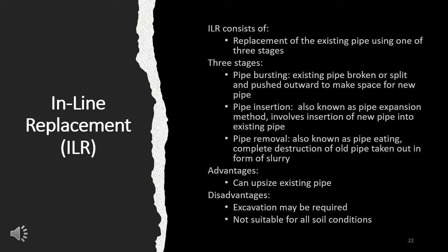Now, some of the advantages of using this replacement technology is that we can upsize existing pipe. The disadvantages, however, are that excavation may be required and it's not suitable for all soil conditions.